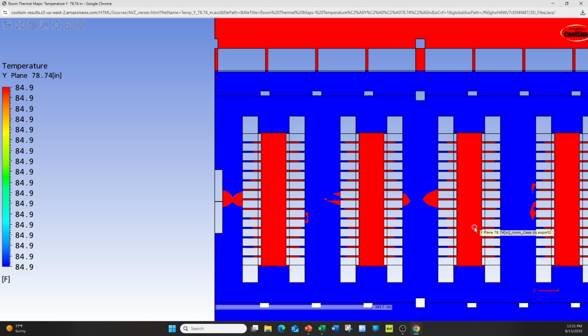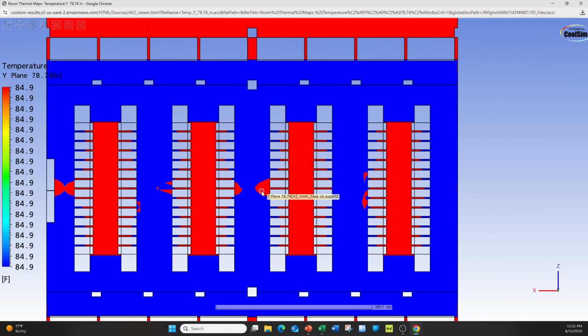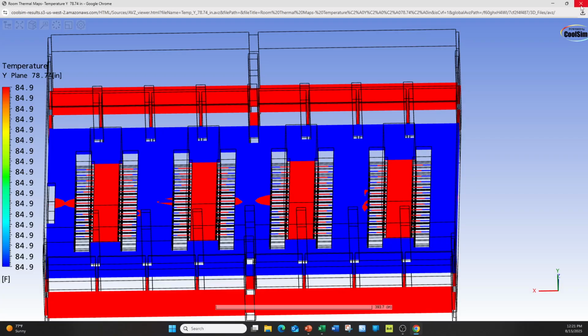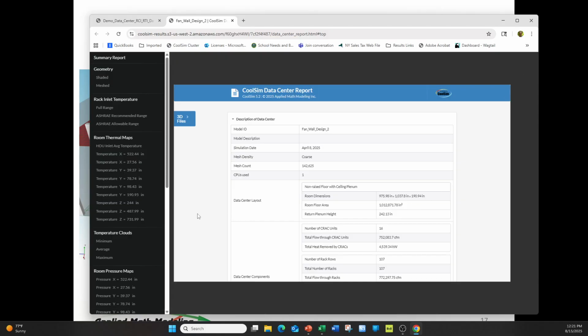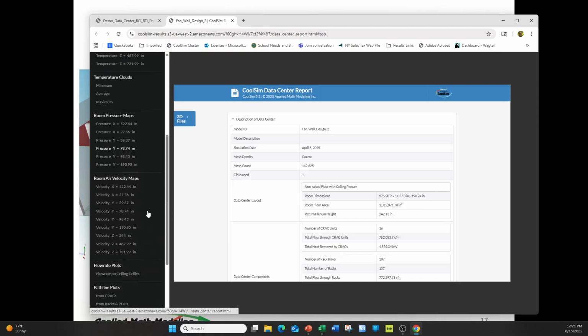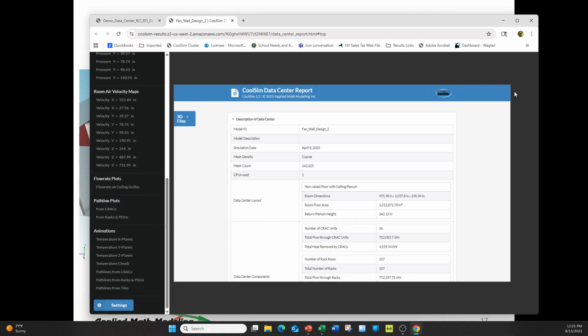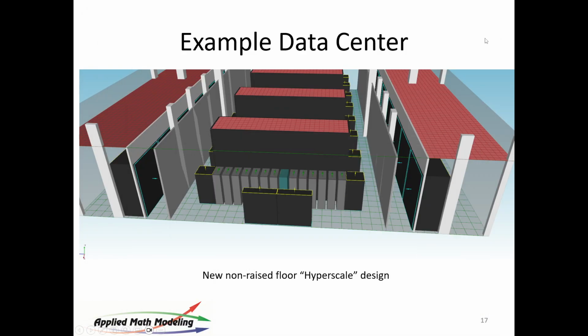So we would look at this from a pressure point of view. We would find that the pressure differential is backwards. And here it's higher in the center, and it is lower outside here. And that's causing it to run backwards. This is a very typical situation that we run into with some designs. I highlighted it here so you could see it. I kind of manufactured this when I ran the supply air just a little low so that you can see the effect of leakage. All systems do leak. All containment does leak. We can look at it from a variety of points of view, including animation sequences, but suffice to say that that is the problem with these kinds of designs.